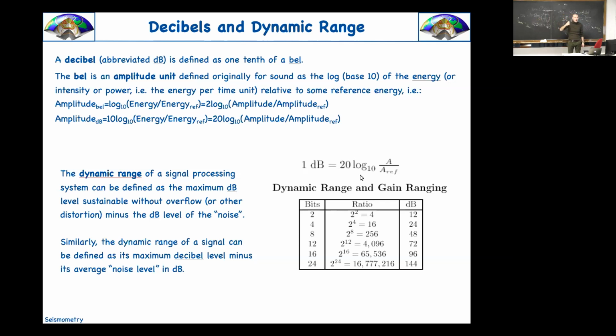That's why you can find the definition of SPL, sound pressure level, and this becomes 20, and that's the amplitude of pressure. For human ears it is 2 times 10 to the minus 5 Pascal. By the way, the 20 here is related to the fact that the intensity is the square of the amplitude.